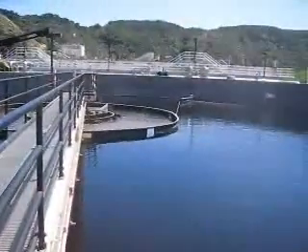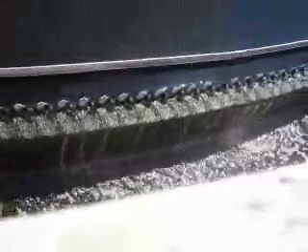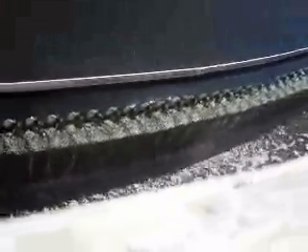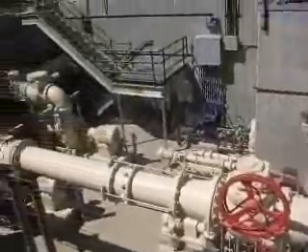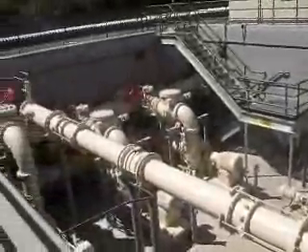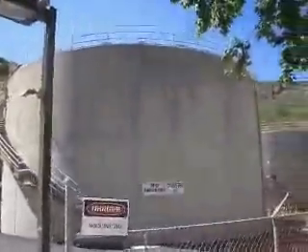After ammonia and other harmful matter have been dissolved, the water goes to one of two secondary clarifier tanks where the microorganisms and solid wastes clump and settle. The water and sludge from secondary treatment is called activated sludge, part of which is returned to the aeration system to refeed the process. The sludge that is not used goes to one of the 3 digesters at the plant.